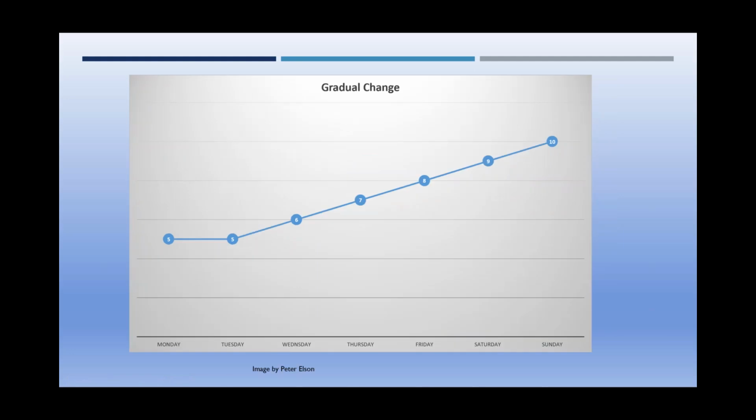So a gradual change is going to be more like, that's funny, Wednesday's a bit higher, Thursday's higher again. Now you know you've got a problem somewhere. You still have to now figure out what it is. But it's probably not from an excavator breaking a pipe. It's more likely to be a leak in a house, a leak in a curb stop.